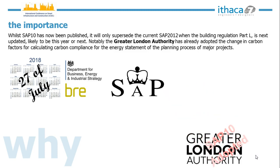As I said, SAP 10, just a little bit earlier, London GLA has actually adopted SAP 10 ahead of the game. So anything on a greater scale, which according to London GLA is over 10 flats or 1,000 square meters covered, will need to be calculated based on SAP 10. Smaller projects, like 8 or 9 flats, can still go with SAP 2012. They don't have to comply with SAP 10.